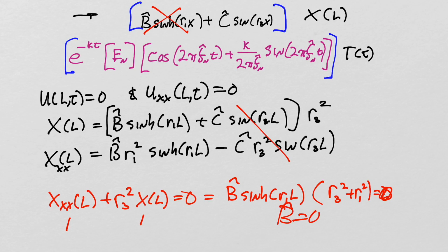Wow, so we did all that work to get down to the fact that the shape of the mode is still, just like in the damped case and just like in the ideal case, just a straight up sine function, just like the other two circumstances. So the stiffness does not end up changing the shape of the mode, at least under these circumstances. So that's interesting.